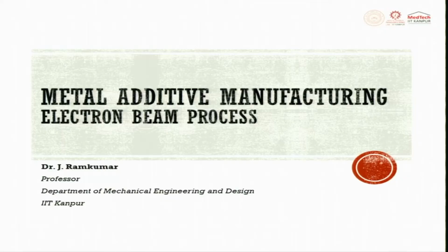Welcome to the next lecture in the course Metal Additive Manufacturing on electron beam processing. In the last lecture, we understood a little bit of fundamentals about laser: why in laser they talk about 2 level, 3 level, 4 level. Second thing is we were trying to look into M square value. We were also trying to look at theta, the beam divergence.